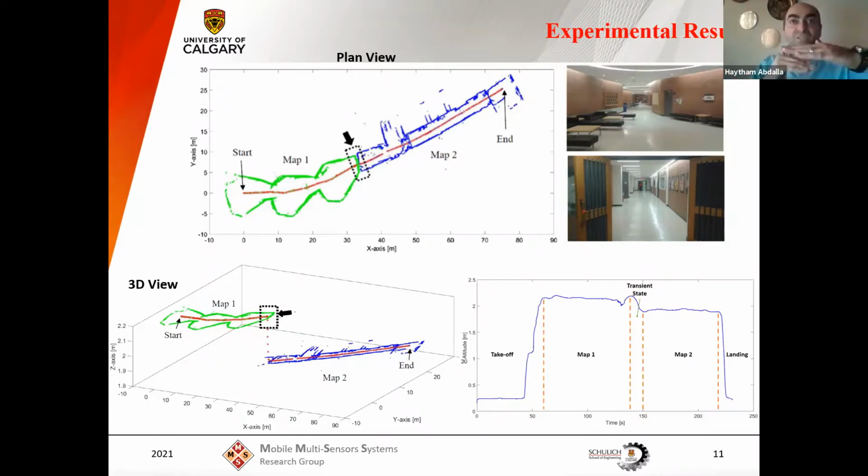During this transient state, the vehicle flies downward, maybe makes some yaw, in the hope of finding a new gap. And when there is a space of more than 6 meters, which is the maximum detection range of the laser scanner rangefinder, it is a new gap.